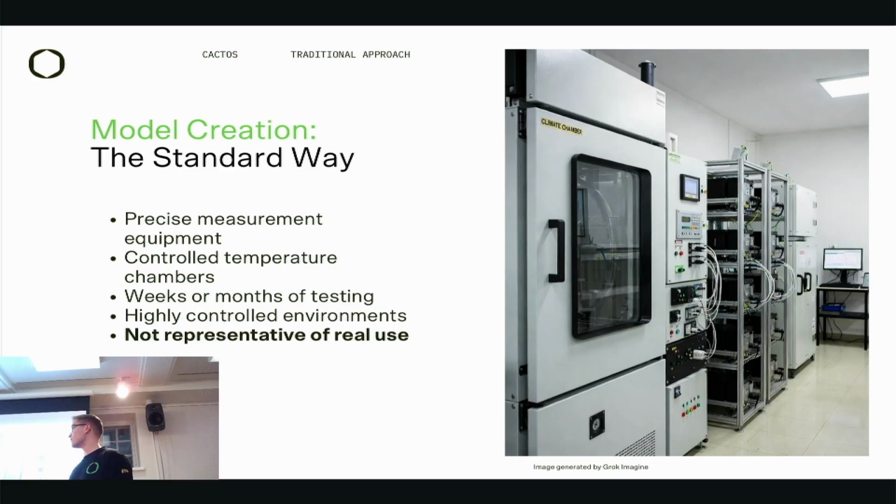The standard way is extensive laboratory testing. For this, one needs precise measurement equipment, controlled temperature chambers, as well as specific testing procedures that can last weeks or months or even years. This testing can be expensive and it's often not representative of real use case because the cells are in such a highly controlled environment.